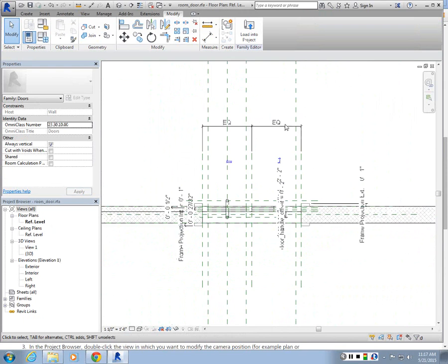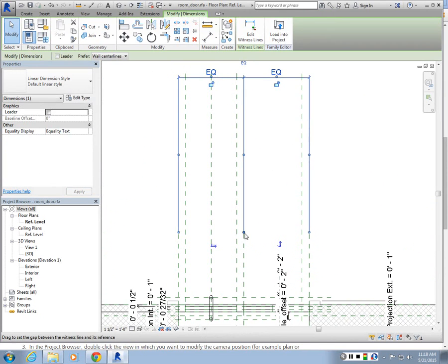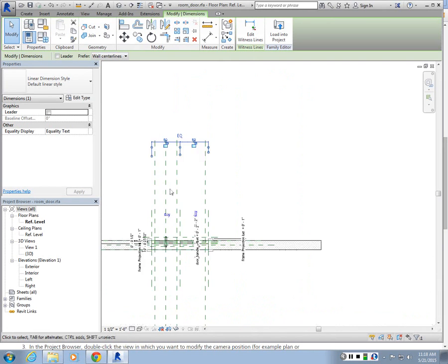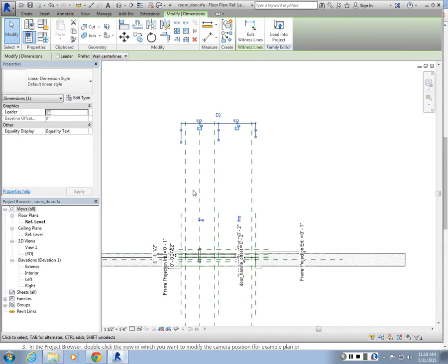And this is actually pretty straightforward. You just model some lines, and then you override what you want to see in a plan view, elevation view, and a 3D view. So you can filter through these elements. You can also add two-dimensional model lines here and use them for drafting, basically.